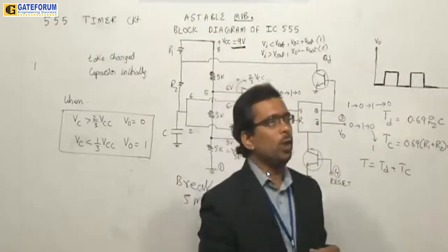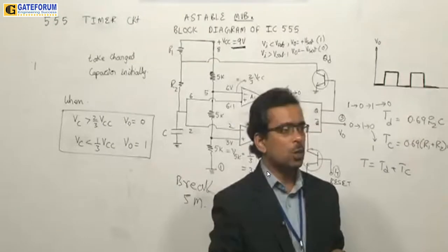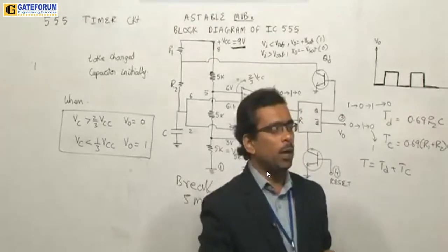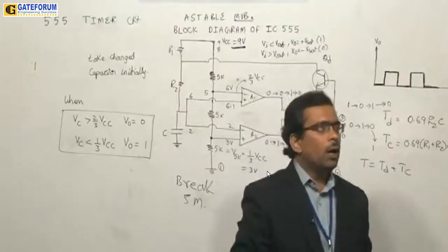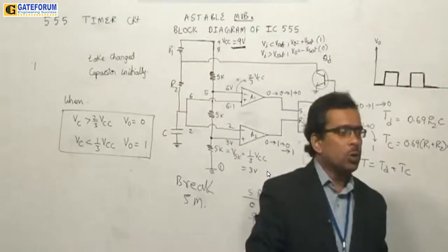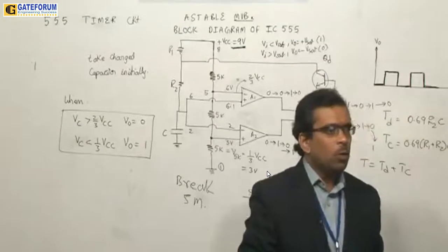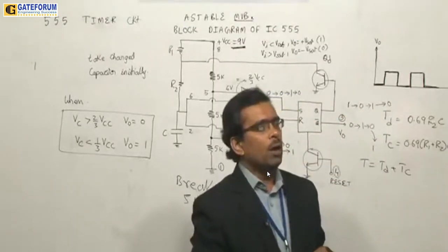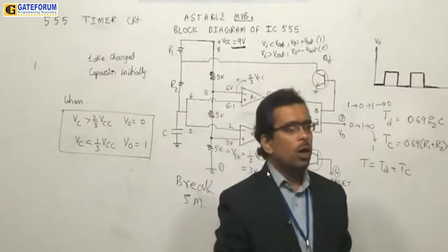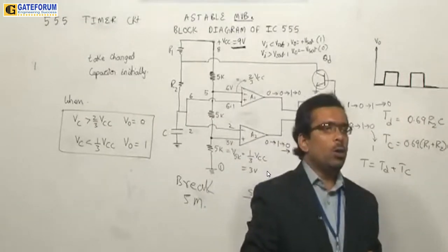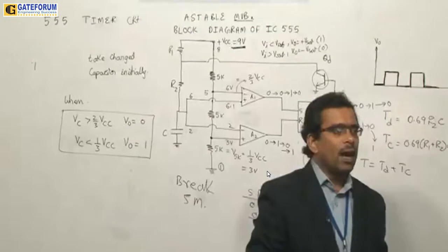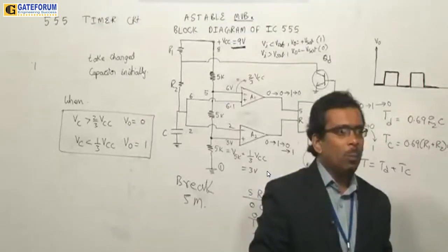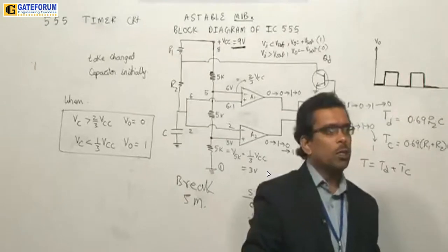As a result, the width of the output is now independent of how long I am holding the input trigger switch on. The output goes low after the decided value of T no matter whether I hold the switch or not. Now to trigger again I have to release the switch, then press it again. Why is it happening so?